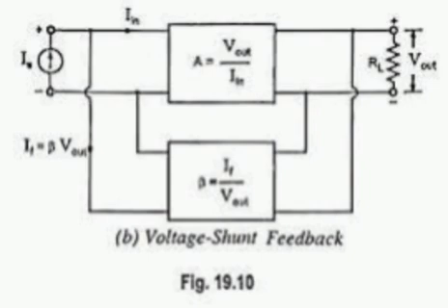Miller effect occurs in CE and CS configuration. It causes an increase in input capacitance. HF analysis of CS amplifier is the same as that of CE amplifier.